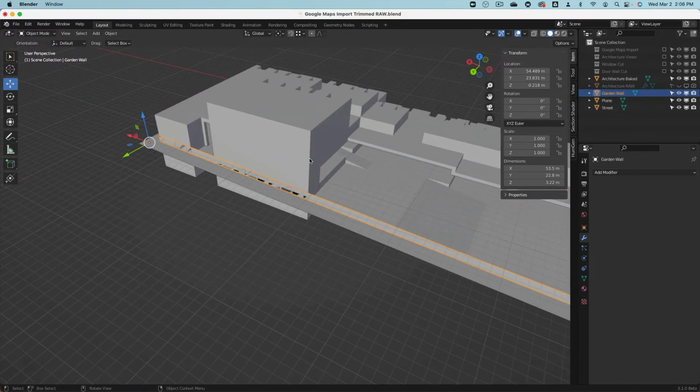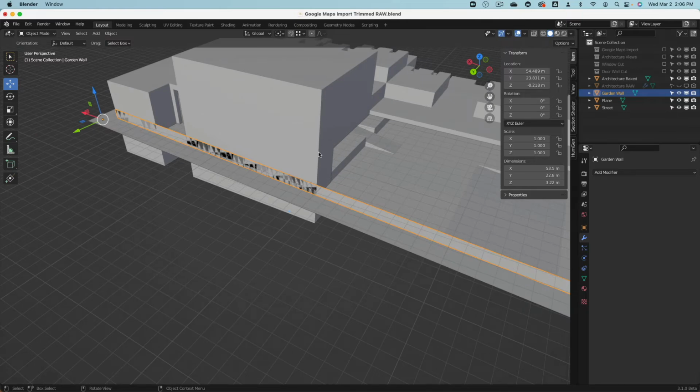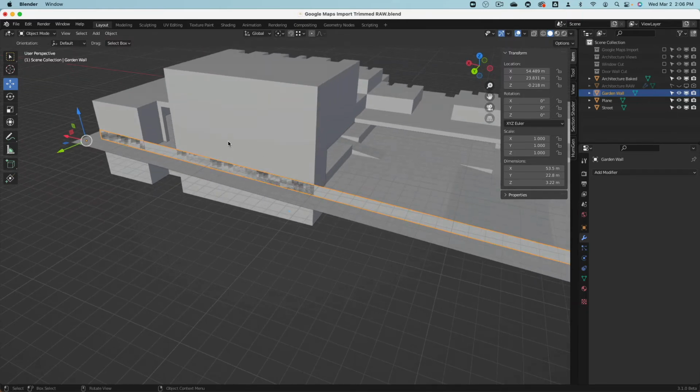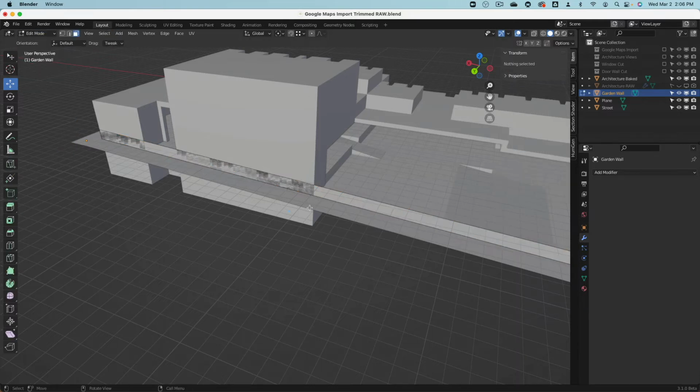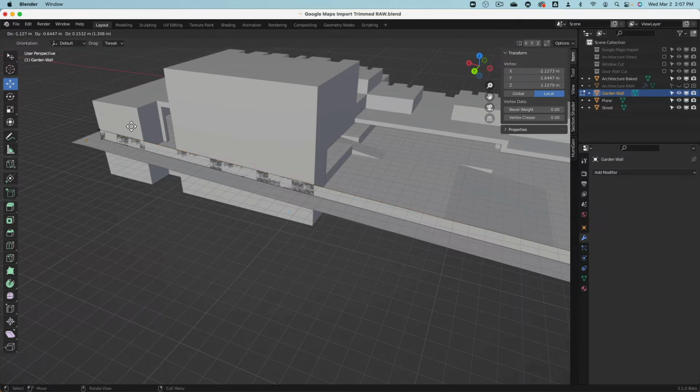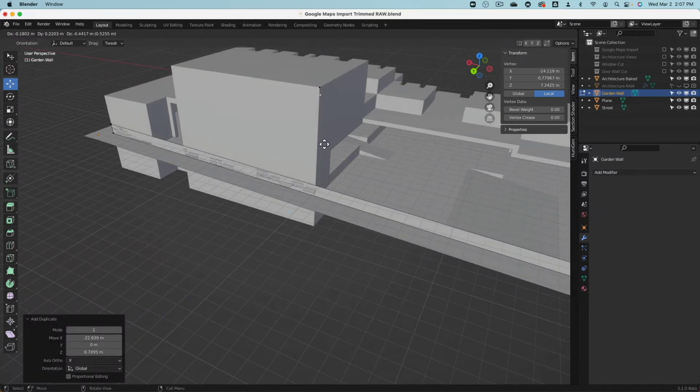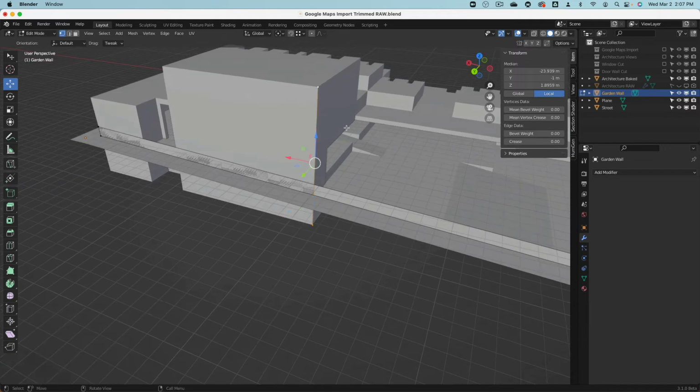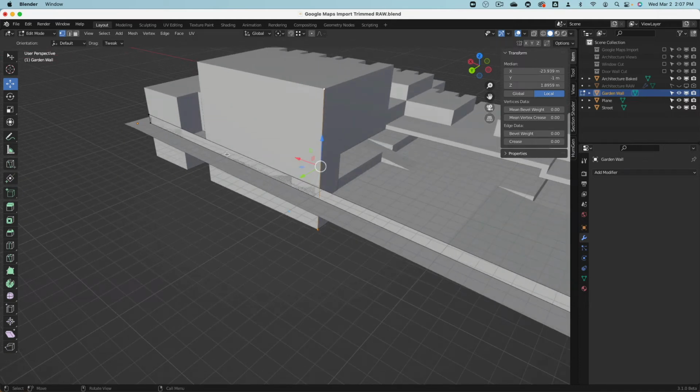Very good. Here I also have this edge and would like to work a little bit precise. So check out this little AutoCADing. So we go into edit mode. There we are now. So this right now I want this to be perfect. So I will select this point and Shift D, make a point, and this point I snap to there. Hold Control, click. E, go down to here, hold Control, click. So you see now I redraw myself a line and aligned it there because, well, as you guessed it,